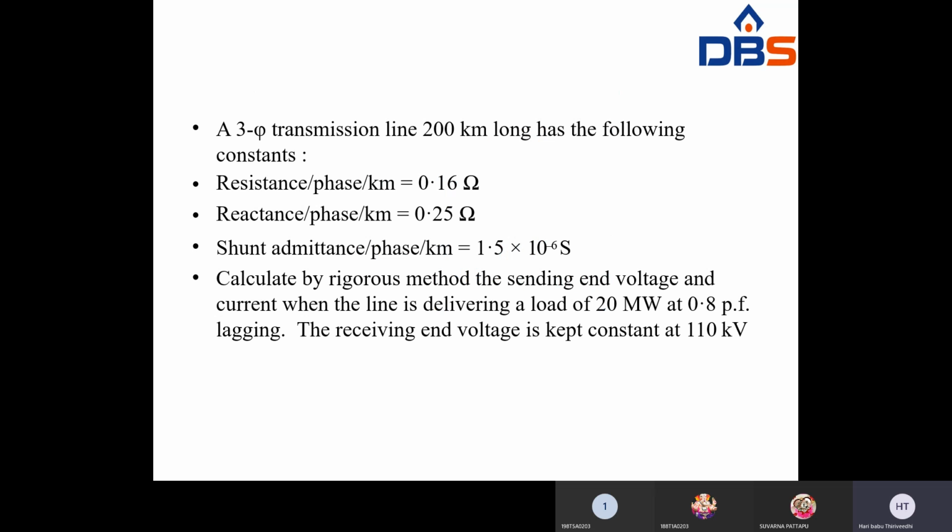First root zy, that is equal to root of z, 59.4 at an angle 58 degrees, multiplied by the y value, 0.003 at an angle 90 degrees. So root zy is equal to 0.133 at an angle 74 degrees. Therefore zy, squaring the value, zy is 0.0178 at an angle 148.